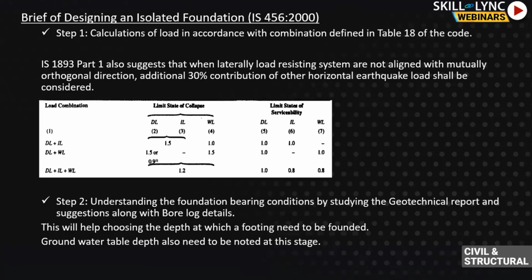All right, so as I explained a little earlier, the geotechnical report will suggest what is the bearing capacity of soil that we are considering for such foundations. And what would be a suggested depth of foundation for the plant or the location or a specific bore log location for that matter.